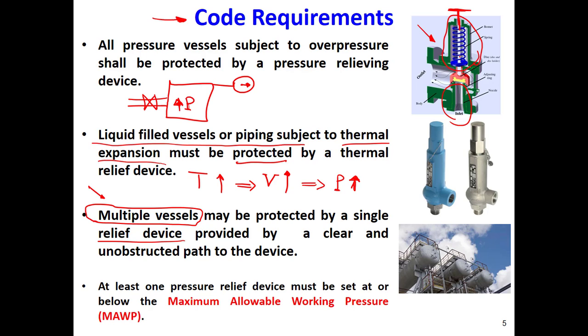By changing the tension of that spring, you can change the relief pressure, the pressure at which the valve has to open or close. You can change it.